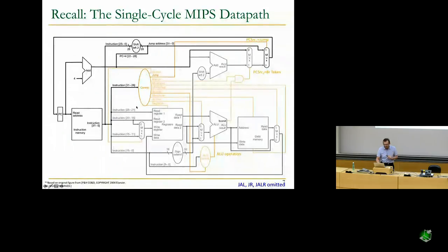And basically this is the control logic. See, over here it takes the instruction, actually the top 6 bits of the instruction, which determines your opcode, and generates these control signals. And there's also some more control over here, which is the ALU control. This tells you what ALU operation you should do, depending on the type of the instruction. And there are a bunch of other control signals that are generated during the operation, in the combinational logic itself over here, not just directly from the instruction, but from the combinational logic. We will see each of these signals over here.